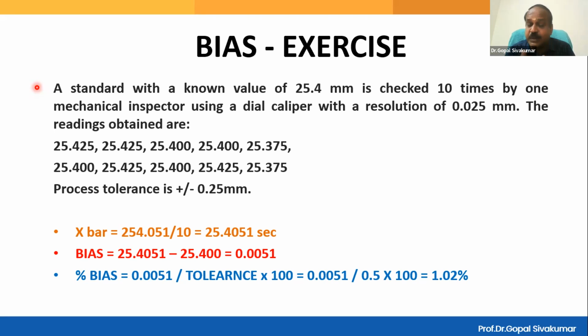But how much is this bias with respect to your working range? That is important. You are buying gold, with a 0.5 gram bias. Are you okay to compromise 0.5 grams? No, no, no. We need to be accurate. Because it is gold, 0.5 gram is unaffordable. If they say 0.05, maybe it is affordable. Or you may even expect a better equipment, 0.005. So always understand your working range.